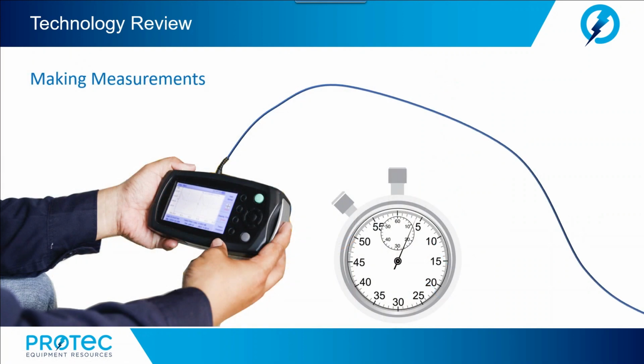Now, knowing that these events are in the cable is beneficial, but to be helpful, we need to know where they are in the cable. Now, we discussed that a TDR sends pulses along the cable that are reflected when they encounter a change in impedance. The TDR times how long it takes for the transmitted pulse to travel along the cable and the reflections to get back to the unit.